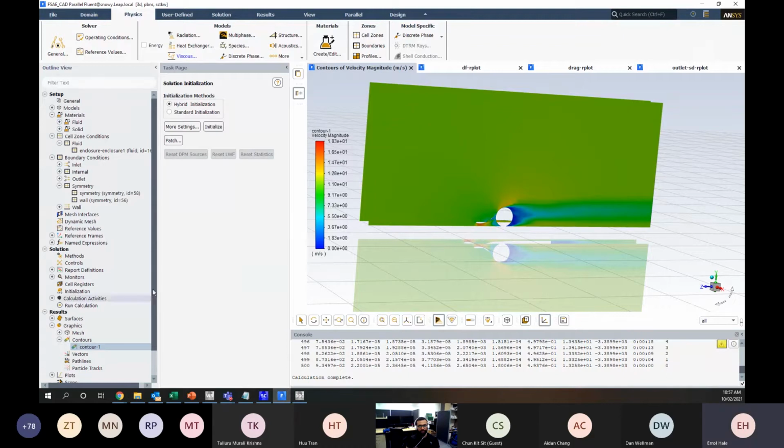Angus, how do we choose between K epsilon and K omega? That's a difficult question. Depends. It's case specific. Most external aero flows, I'm going to use K omega SST, because SST stands for shear stress transport, and it's a really good way of picking up what's happening in the boundary layer, which we'll go through in a bit when we go through boundary layer modeling. K epsilon's also pretty good.